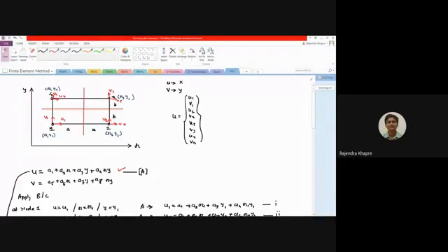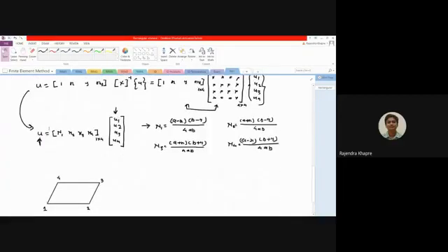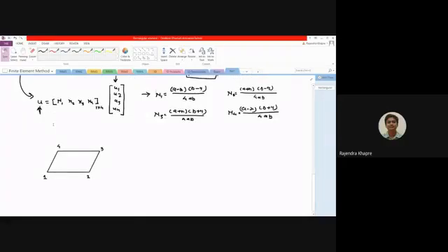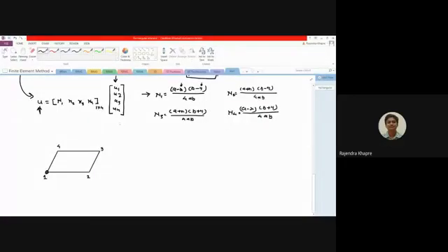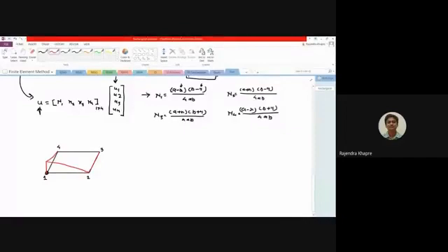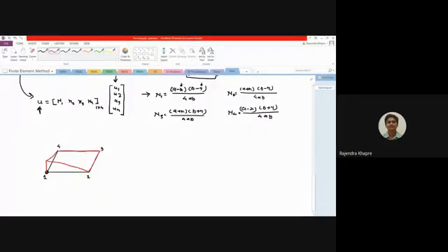So you can substitute these values in this particular expression, and then you can get the variation of the shape function. Whatever value of x is there, let us say your joint coordinate is starting from here, then definitely the value of x will be 0 and the value of y will be 0. So accordingly you are going to get a variation. Here the variation will look something like this. The value of the shape function will be 1 at this node, but at the other nodes it will always be 0. This type of variation we have also seen in the CST element.